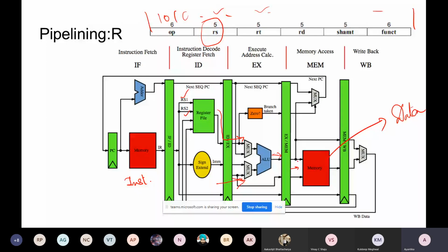So here, see, there are two inputs. The same ALU output is either going to this memory or it is going to this part. Again, I will come to why this mux is there. This part is going back to the register file. That means this is a write back. It is getting stored in our register file. So this way, you can see how these individual components are helping us to actually execute our requirement.